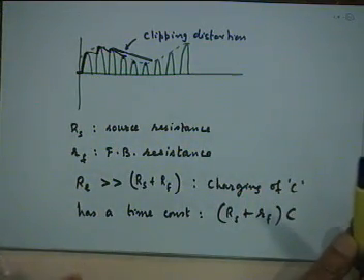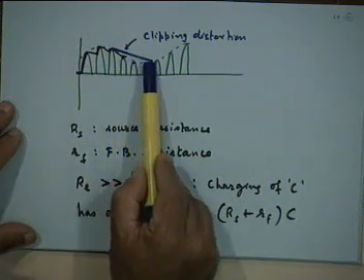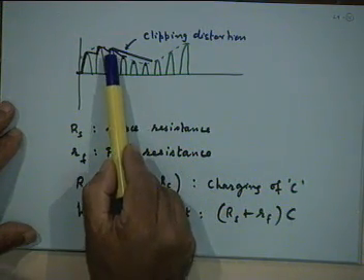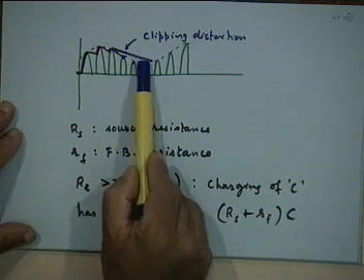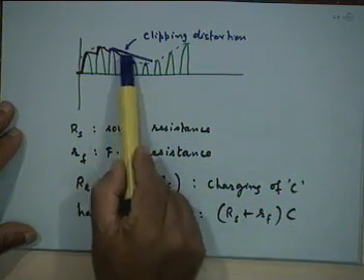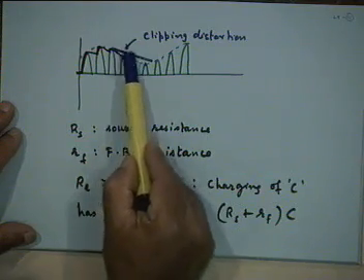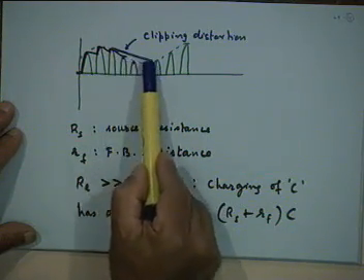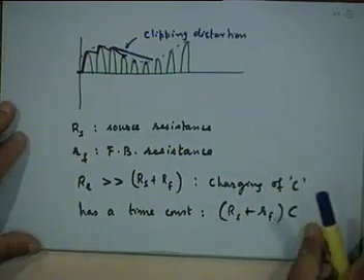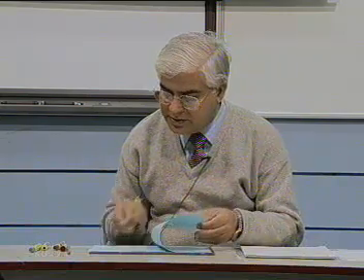You just want to make sure that while the rate of discharge is slow, it is not so slow that you miss the fast fluctuations in the envelope itself, right? So you are comparing this rate of variation with the rate of variation of the message waveform, the envelope. Is that clear? So the carrier frequency does not enter into the picture at this stage.